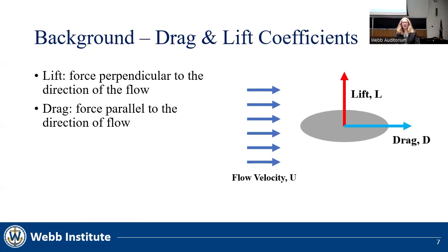While the lift and drag forces themselves are useful for many engineering problems, in this case, we want to be able to compare different geometries. So the lift and drag coefficients are used. These coefficients are shown above and are non-dimensionalized by dividing the force by 1/2 times the water density times the fluid velocity squared times a characteristic cross-sectional area.